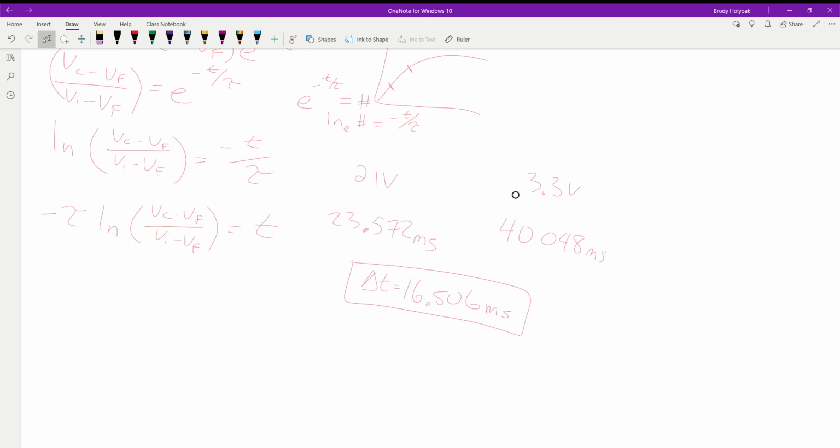So it's going to make it choke and give us some random output of our circuit. So if we can get this up to where this is fast enough to where we're sampling it, maybe we'll catch one in here, but odds are we're going to catch ones on the outside and on the inside of where we want it. We want to see it low, and then it'll change so it's high. But just know that, that's kind of the scary zone. That's why we need to know how much time is there so we can build around it.